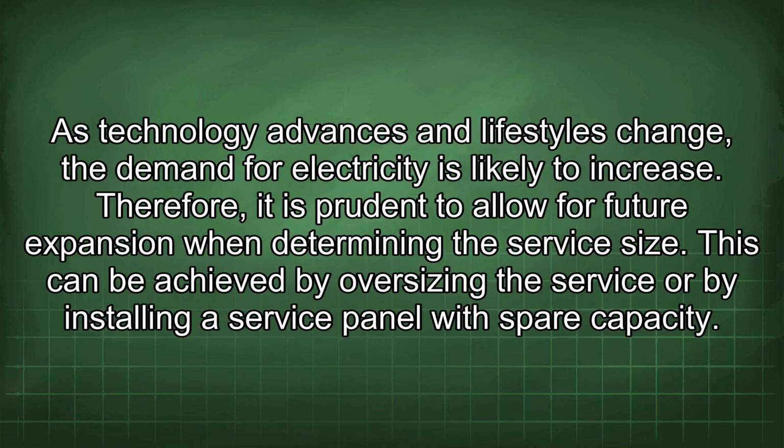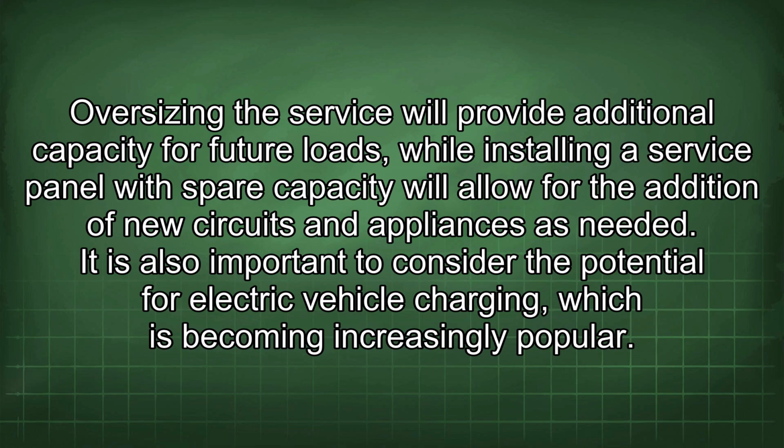As technology advances and lifestyles change, the demand for electricity is likely to increase. Therefore, it is prudent to allow for future expansion when determining the service size. This can be achieved by oversizing the service or by installing a service panel with spare capacity. Oversizing the service will provide additional capacity for future loads, while installing a service panel with spare capacity will allow for the addition of new circuits and appliances as needed.